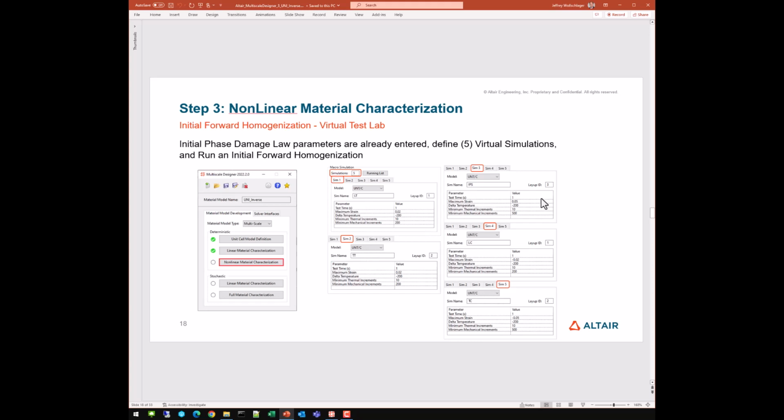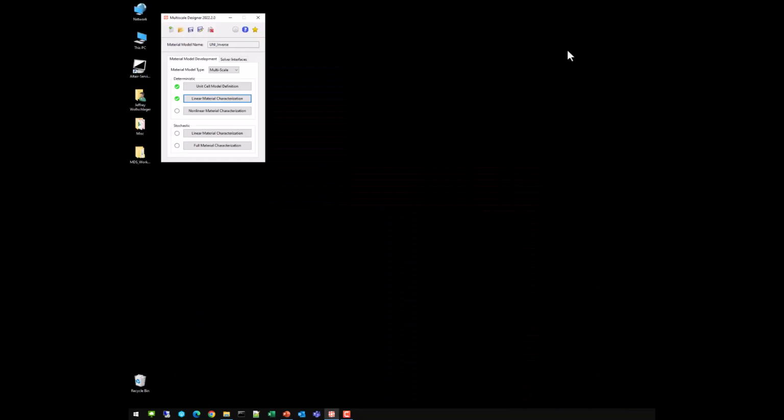Those were defined in video session 1. They're the same definition. So longitudinal tension is the 0 degree tension. Transverse tension is my 90 degree tension. IPS, in-plane shear, is the plus or minus 45 tension. LC, longitudinal compression, 0N compression, and TC, transverse compression, is my 90 compression.